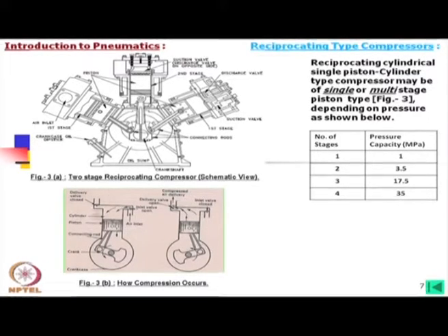This is the simplest form of this reciprocating system, with just suction and compression, so in and out delivery. So, for one cycle, half the cycle is suction and half the cycle is delivery. So, you can put two cylinders, single stage, in such a way that continuously it is supplying the air.